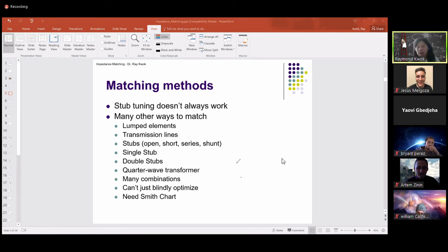Last time, people designed an amplifier by buying a MMIC here and biasing it. And then on this side, here's a shunt capacitor and the inductors. And so that would match. This one has a shunt capacitor and series capacitor here. It will match. So now this is my input matching network and output matching network.